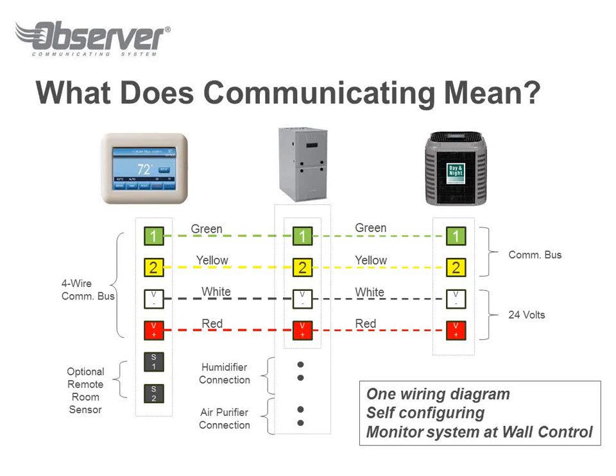So that helps you out with wiring distances, because generally the humidifier is directly above the furnace, and wiring the two together is very easy. Same with an air purifier. If you choose to put one of those on the unit, we can enable that off of the furnace circuit board. Then you have the outdoor unit, and it also can be a communicating piece of equipment.